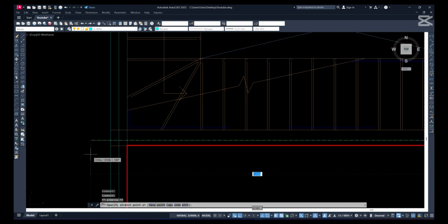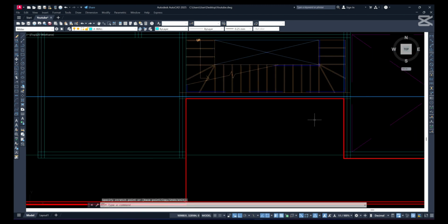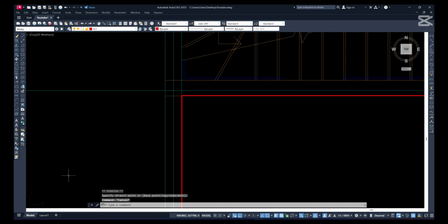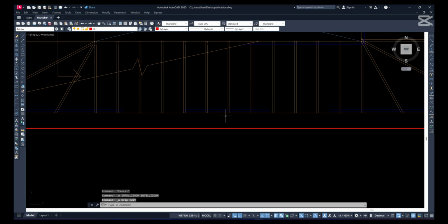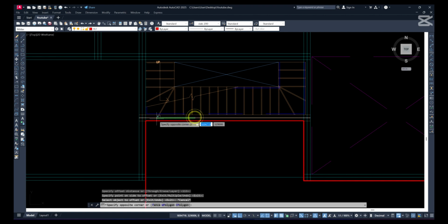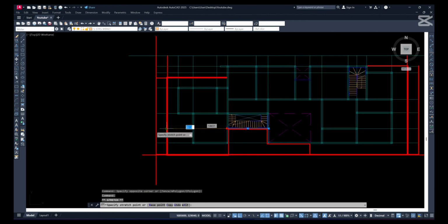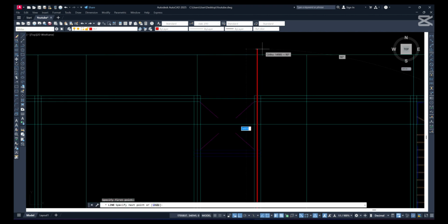So you see, I just checked. The grid line is now at the center of this other beam. See, here it's not at the center, so I have to make sure this beam has a different grid line, since the other grid line is not on the same level as that beam. The grid line doesn't cut across at the center of this other beam. So now I'm forced to create a new grid line for that beam. But when the grid line cuts across the other beam at the center, you just let it go.